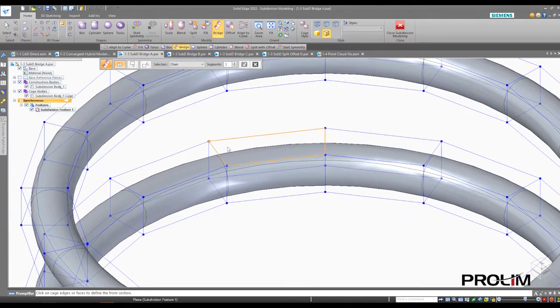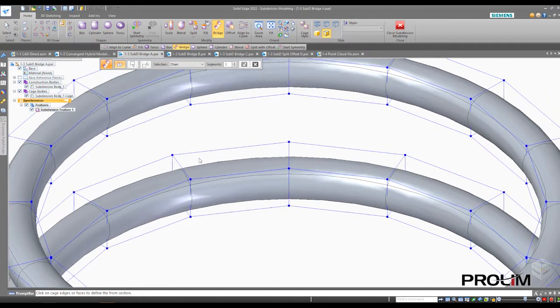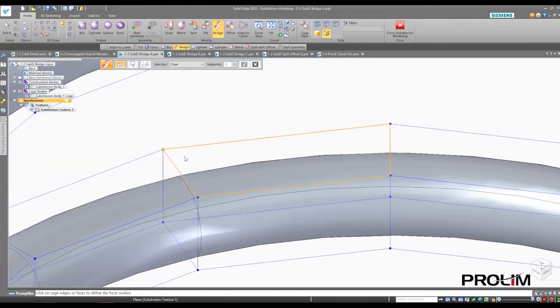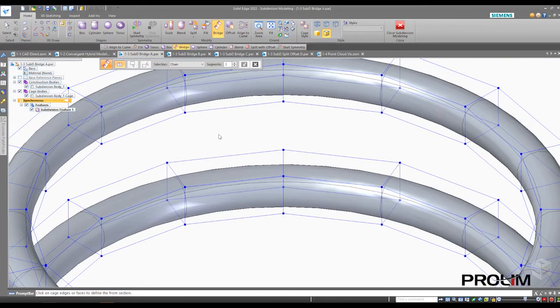I want you to pay attention to, when I select a cage, it's kind of hard to see here against this white background, but if you notice this top left-hand corner, it's got a little vertices here. The location of my cursor is going to basically identify the closest corner or edge that it's predicting that I want to select. So keep that in mind, because if you're familiar with the sheet metal lofted flange, it gives you kind of a preview of the vertices.